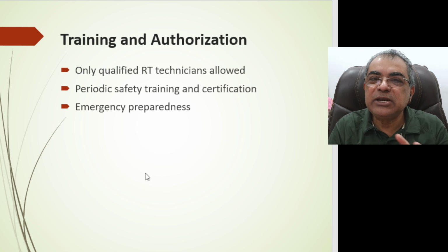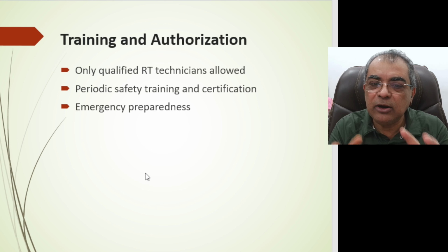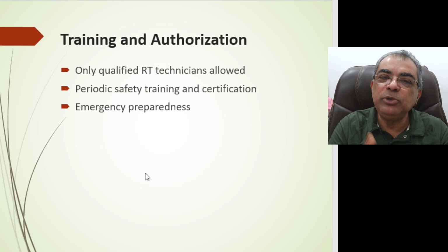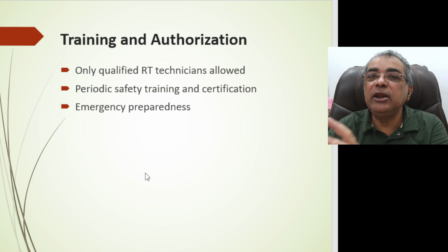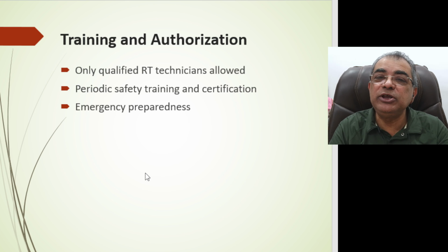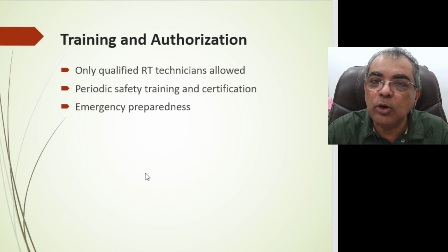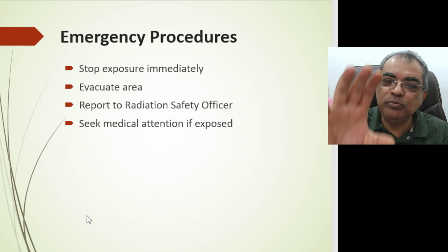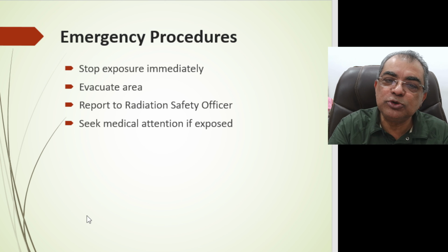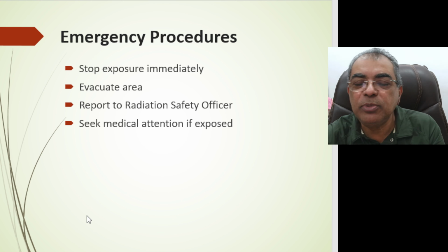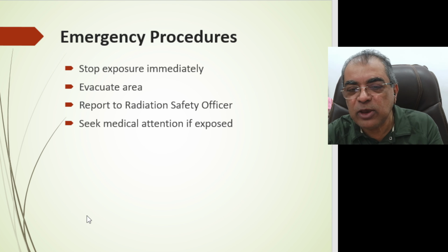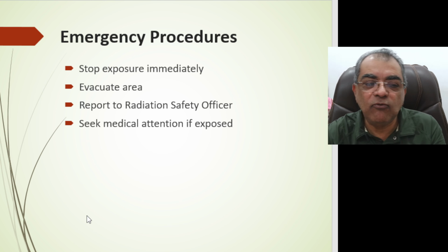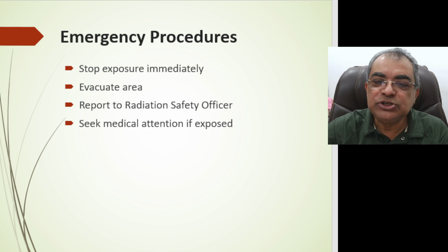Anyone involved in this radiography work has to be trained and authorized. No unauthorized people, and periodic training is needed. You have to prepare emergency preparedness, because if the source of radiation fails, what are you going to do? When preparing an emergency procedure, you have to define how to stop the exposure, how to evacuate the area, where to report, and what medical assistance you need.